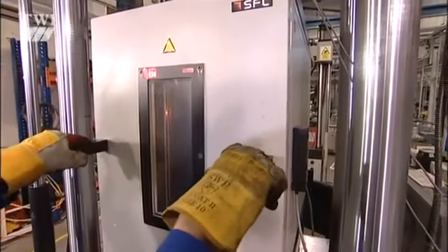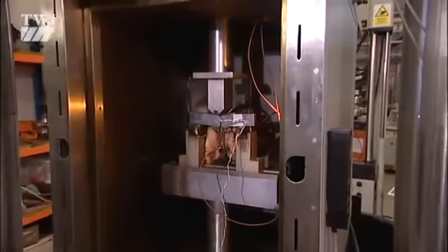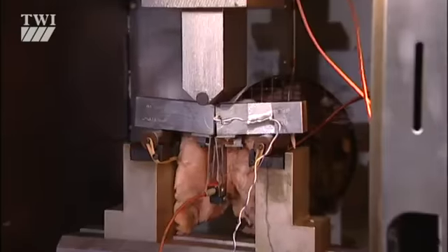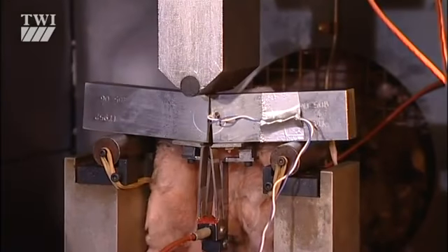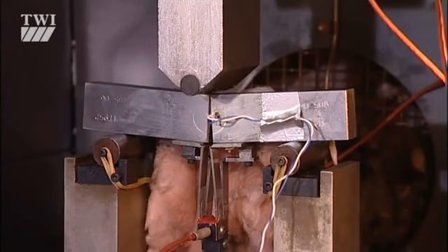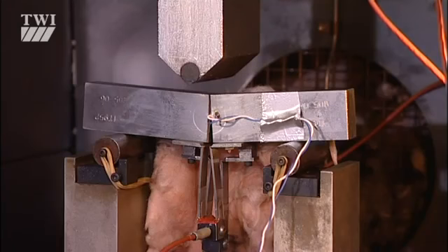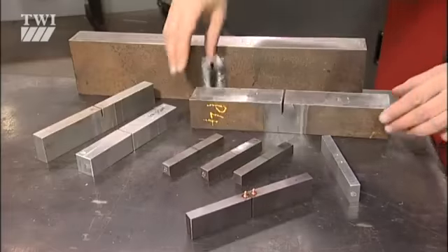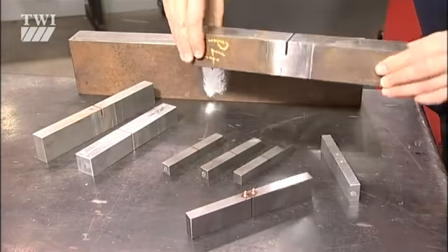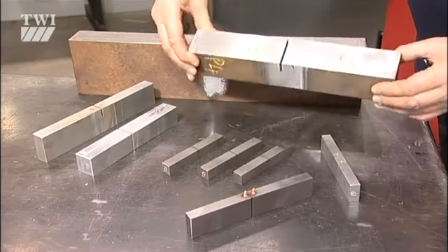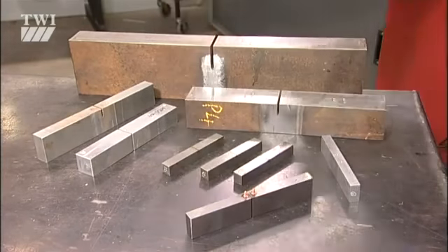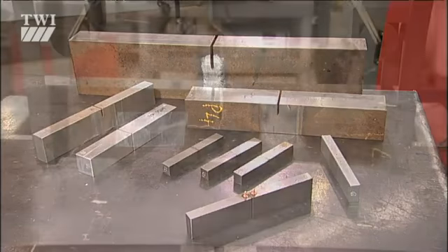Measuring fracture toughness accurately, in a way that can be related to a tolerable flaw size, is a job for the crack tip opening displacement test, or CTOD as we call it. Unlike the small, inexpensive Charpy specimen, the CTOD specimen may be the full thickness of the material.